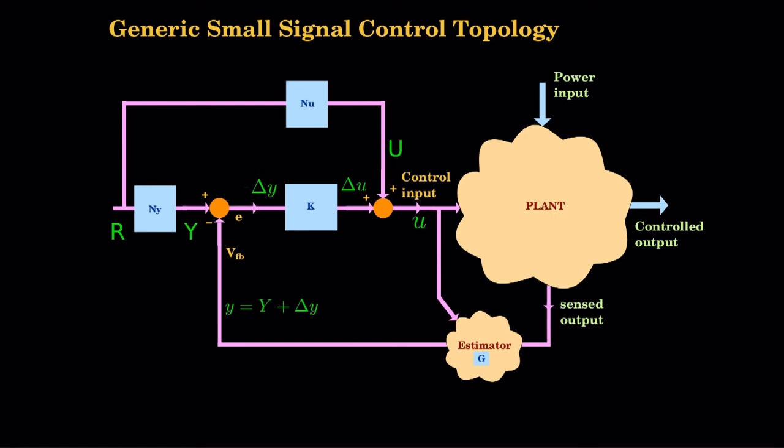And the beauty of it is there is no trial and error. These are closed form solutions. If I have 4 Ks to be determined, K1, K2, K3, K4, 4 states are there, 4 Ks to be determined, I have 4 equations, 4 unknowns, you will precisely be able to find out and plug in. Same way for G, you will be precisely able to find out and plug in. That is why I said they are 5 minutes job. In 5 minutes, G, K, NU, NY, you should be able to, 5 minutes is too much. For whatever time the computer takes to compute, it will give you the values. You plug it in, it should work.